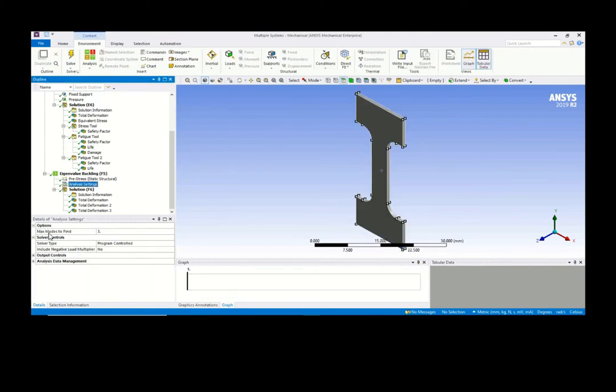The question asks you to find the maximum 3 modes, so you have to set this to 3. Then remember to exclude the negative load multipliers, so you are getting all the positive loads. Positive load means coming down in compression, not the pulling types. So all are compression types.